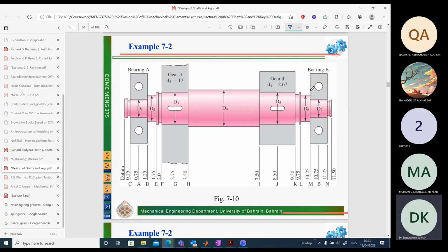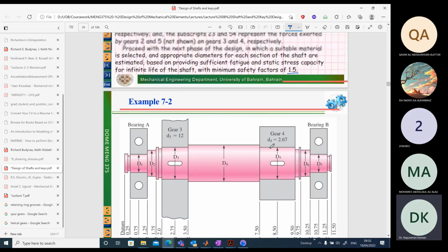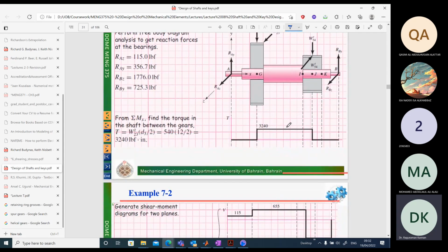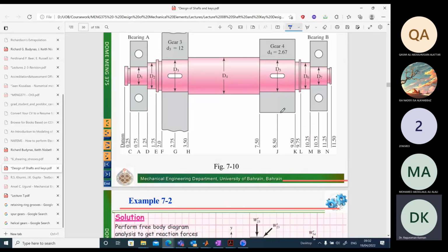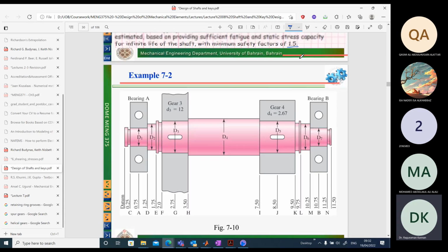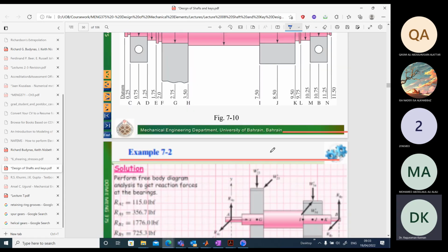Go back here. Where is the groove? Groove is located here. Now up till the key seat, we have the torque. Where is the torque diagram? Let's go below here. Up till this point J, up till the key seat here, we have the torque, and therefore we had to include the torque. But right after this point J, there is no more torque. Torque is 0.